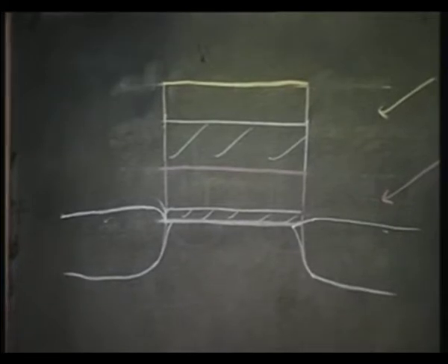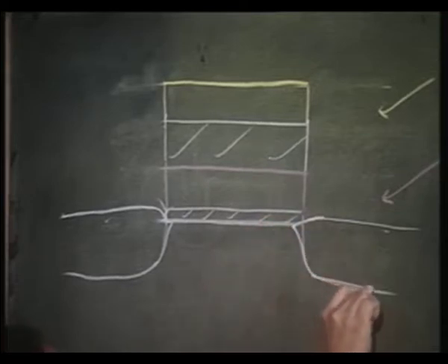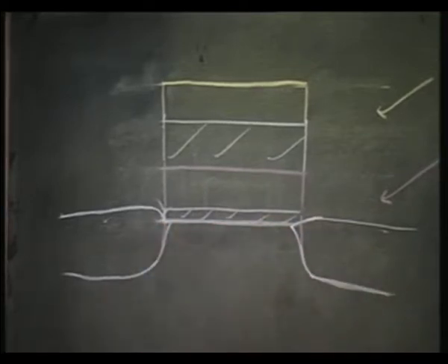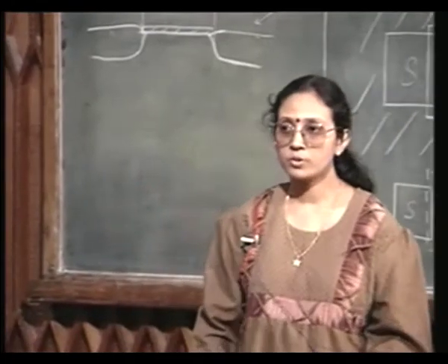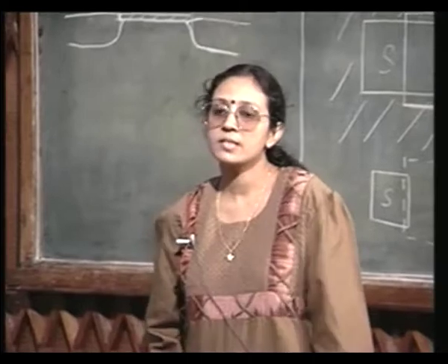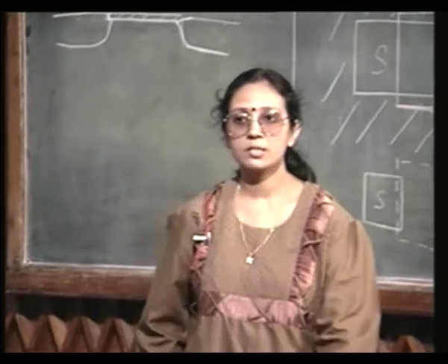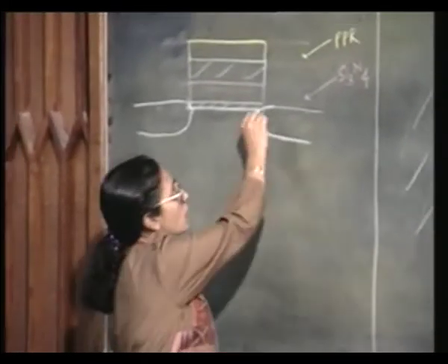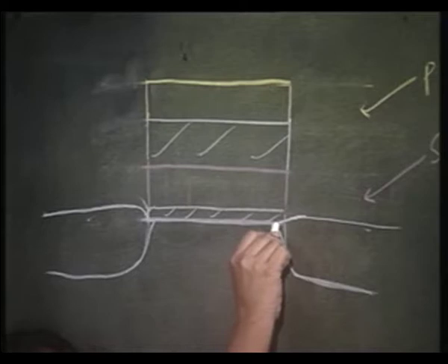You see, this problem of the oxide penetrating a little bit inside is more if you have the thin pad oxide. Okay. So, you see there the silicon surface is actually in contact with the pad oxide, and the oxidation can actually at this corner proceed slightly underneath the pad oxide.